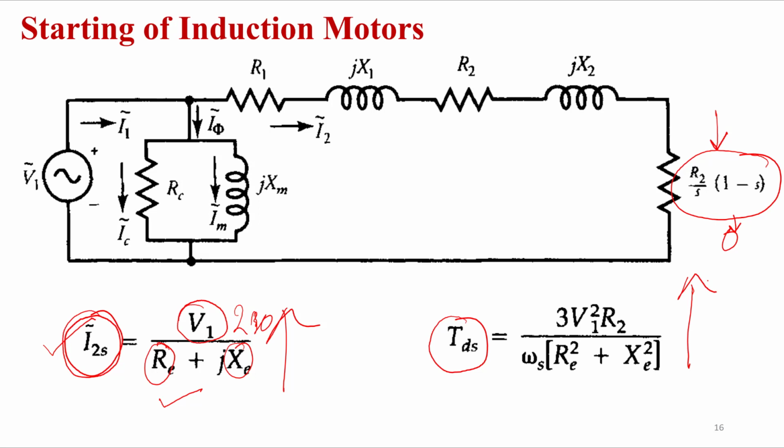which is not actually very useful; rather, it will break the rotor. So it is essentially not required to start the motor by directly supplying or directly switching on the voltage to large induction motors. Small induction motors like a fan you can start, but not large induction motors. Above 5 HP also we cannot start directly.